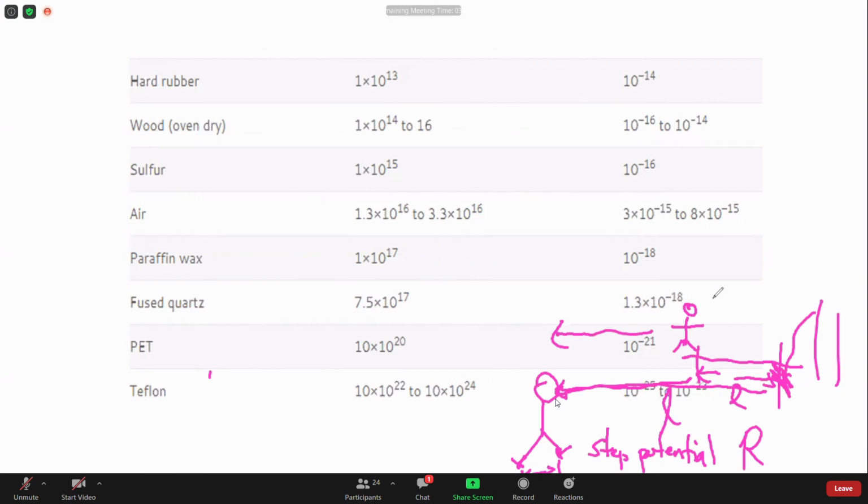That is what is called hopping. The purpose is not to have a large distance between your feet, because if you step left, then right, and left, your step potential, the potential between this foot and that foot, is high. If there is a large potential difference between one foot and the other, there is a tendency for current to flow. The current will run through the body to the other end. If your feet are very close, there is no potential difference between one foot and the other, so no current circulates in your body.